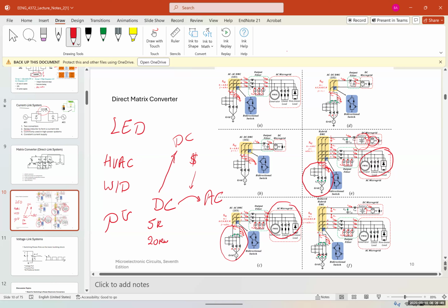The only big problem may be your washer dryer. Washer isn't a big deal. It doesn't consume a lot of power. Dryer is like 4 or 5 kilowatts. And if you have a car, RV or a tiny home, usually they don't have a dryer. You just dry it in the sun, natural drying. So what we can do, we can get rid of the inverter, which is like in this case 4K, and have a DC system, a DC microgrid.